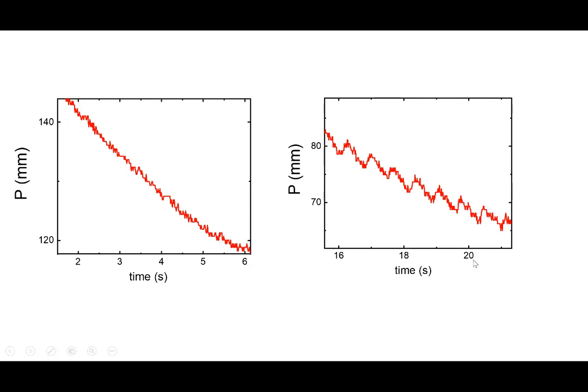let's say 16 to 20 seconds, you can really see a structure here. You can see a variation in pressure: the systolic part where the pressure is high, and then the diastolic part where the pressure is low, and you can see a periodic signal. By counting these peaks, you could count, for example, the pulse rate. So this is towards when the blood is steadily flowing in the artery, and this is how the pressure signal looks. You can see the signal clearly here.